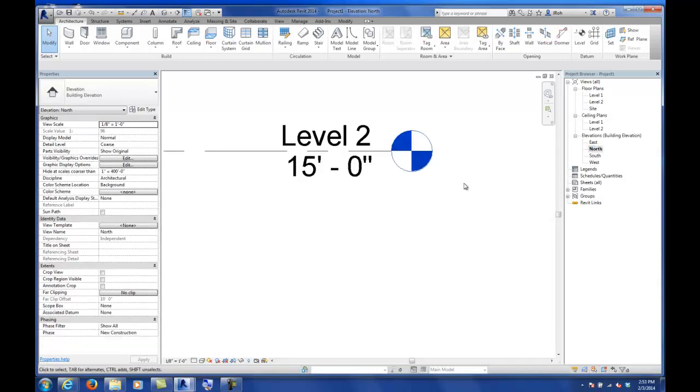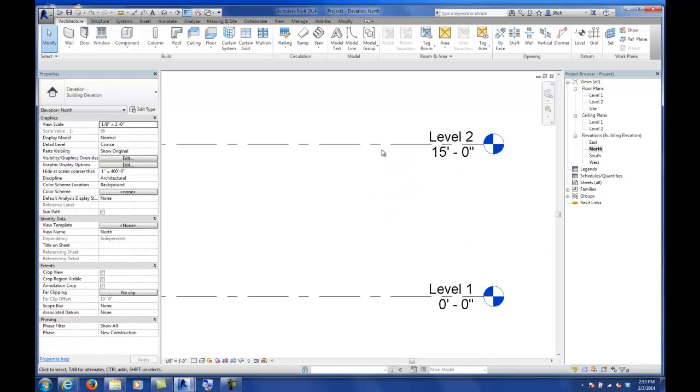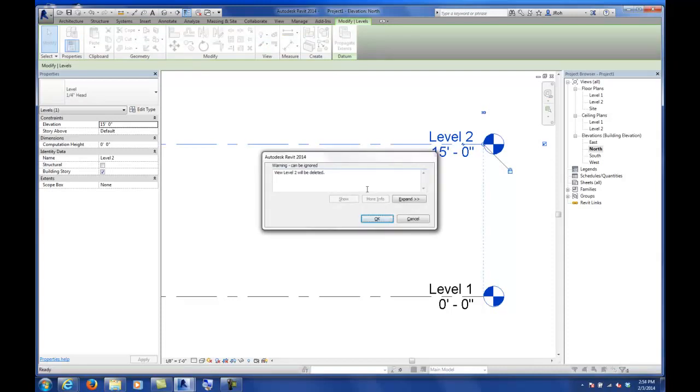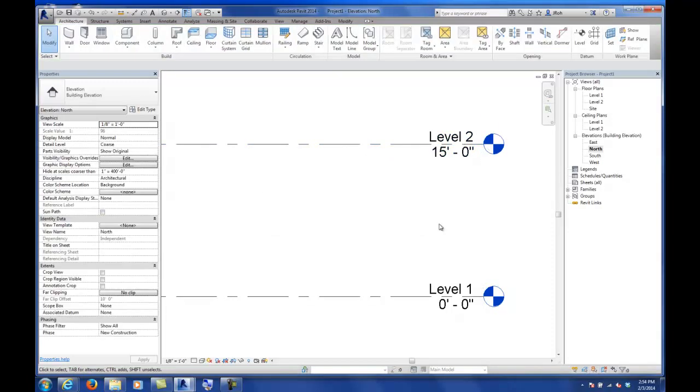If you go back to the north elevation, another thing I want you to be aware of is if you click on one of these things, and let's say you don't want that to show up in your drawing, and you hit delete on your keyboard, you're actually deleting a model view or another drawing that's part of your model. So be very careful what you delete and pay attention to this warning sign, because a lot of times, in order to model, you'll have a lot of different section marks or elevations, and then when you go to print for studio, you don't want those to show up, so you delete them all, and then you lose a lot of work that happened to be in other drawings. We'll get into visibility later, but you can turn those things on and off and hide them. Just be aware of what you delete when you're in these BIM environments.